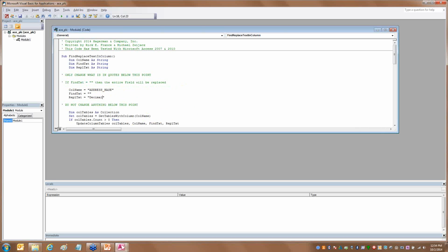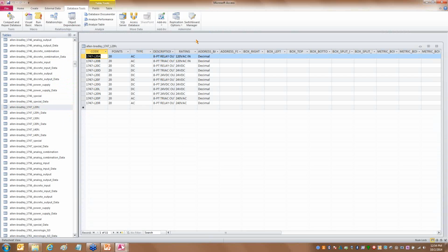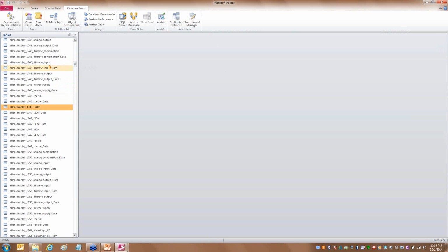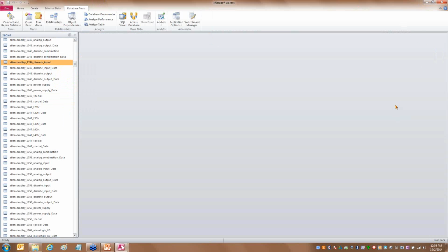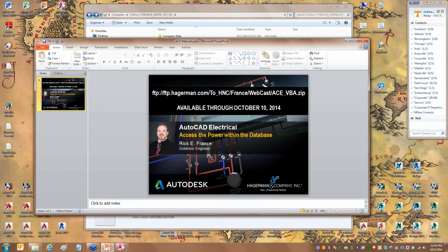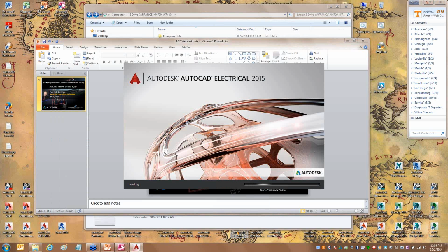I'm going to tell it decimal. So address base, we're going to set to decimal. We'll go ahead and come up here and hit play. It just takes a couple of seconds there. It's done. Come on down here, look at it. You can see it put decimal on all the address spaces. And it did that in every table throughout the product. So I've got my standard set. That's one less dialog box because back here in AutoCAD Electrical, we're going to do it, put our stuff back in and see if it's fixed.